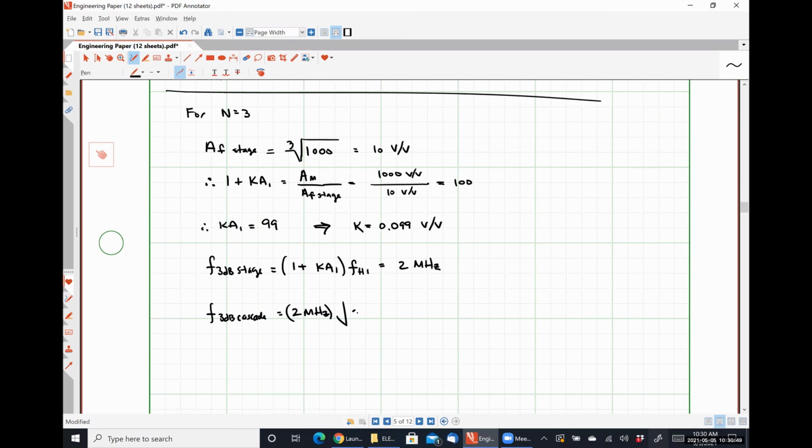times the square root of 2 to the 1/3 power minus 1, which is 1.019 megahertz. So pretty dang close to our design criterion frequency. If we only did two stages, we'd actually come out at around 640 kilohertz, which is well below our cutoff frequency. If we did 4 stages, we'd wind up somewhere closer to 2 megahertz for the overall system, which is well beyond what we were explicitly asking for. So 3 is the magic number based on how these amps behave. So very good guess.